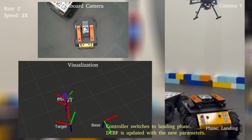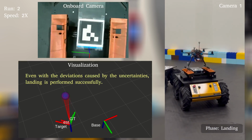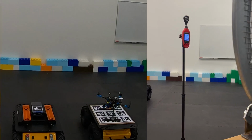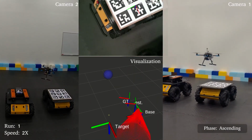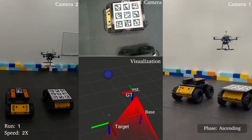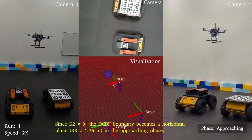The landing CBF ensures the vertical descent of the UAV for a safe and precise landing. An additional perspective of the experiment is provided using the video on the left side. Similar to the previous case, the CBF and adaptive control layers bring the UAV to the safe zone even when it momentarily breaches the constraints due to the uncertainties.